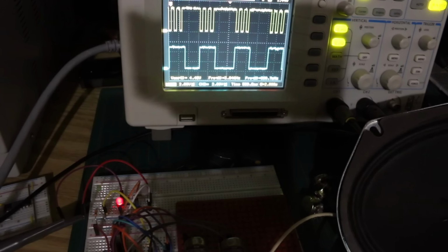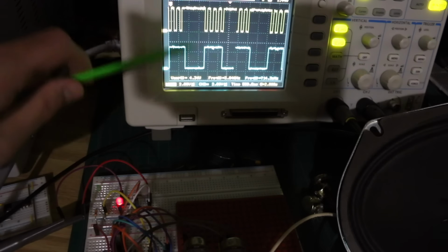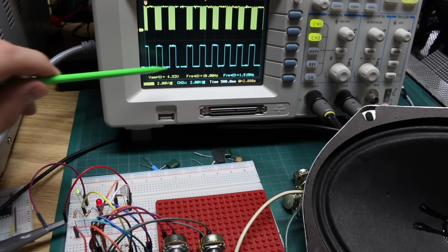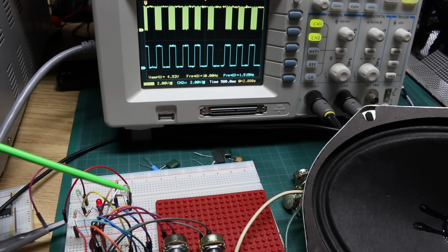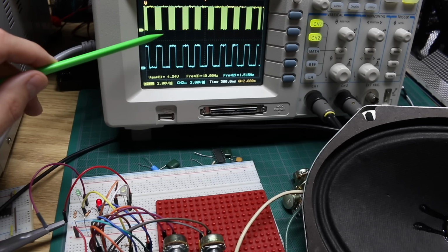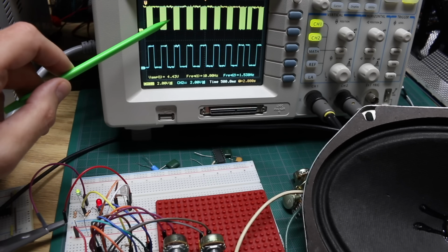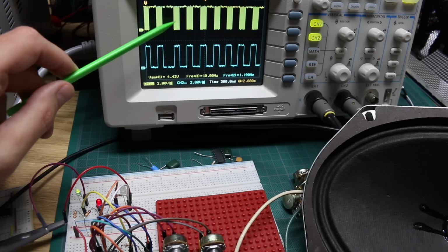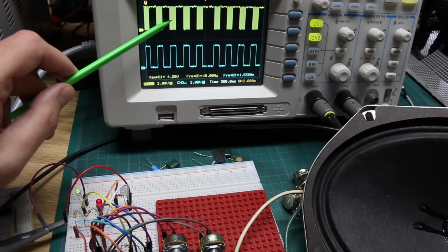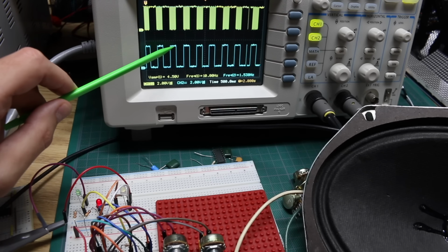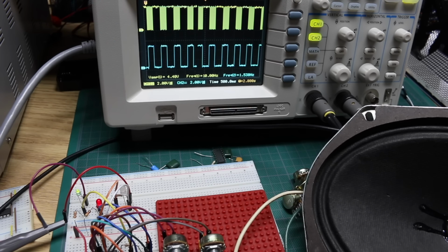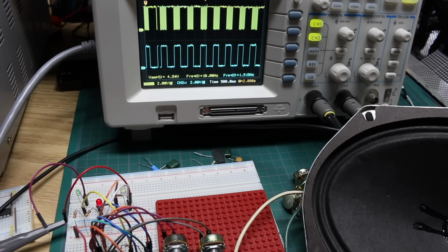But if you connect up a speaker and make a faster oscillator, so I kept the blue trace as a slow oscillator to gate another oscillator now with a higher frequency. I switched out capacitors. So now the final gated output waveform is a higher frequency audio tone only enabled when the slow oscillator allows. So if I hook up the speaker and play around with both the tone and the gating speed,